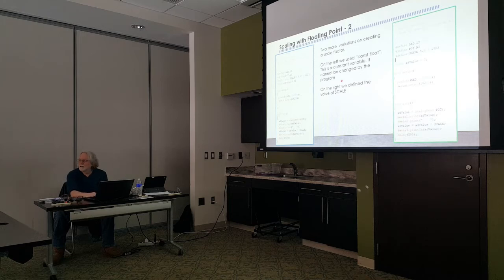One thing that they note in the Arduino manual is that floating point math is also much slower than integer math. Yep, I don't think it has its own processor instruction. Programmers often go to some lengths to convert floating point calculations to integer math to increase speed.